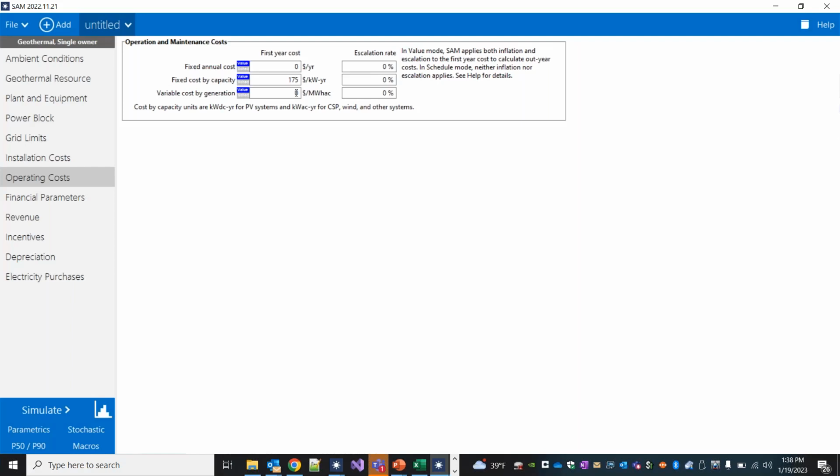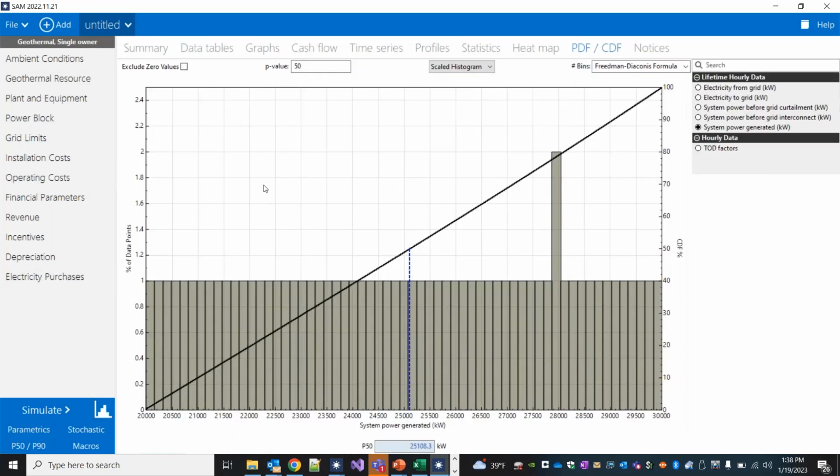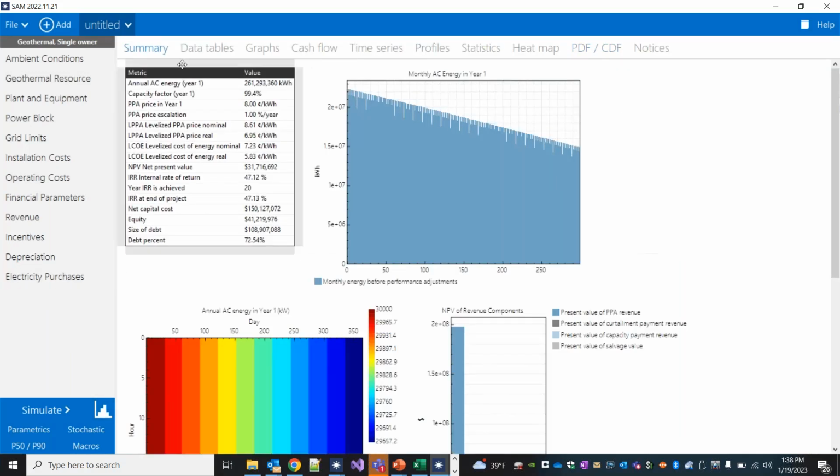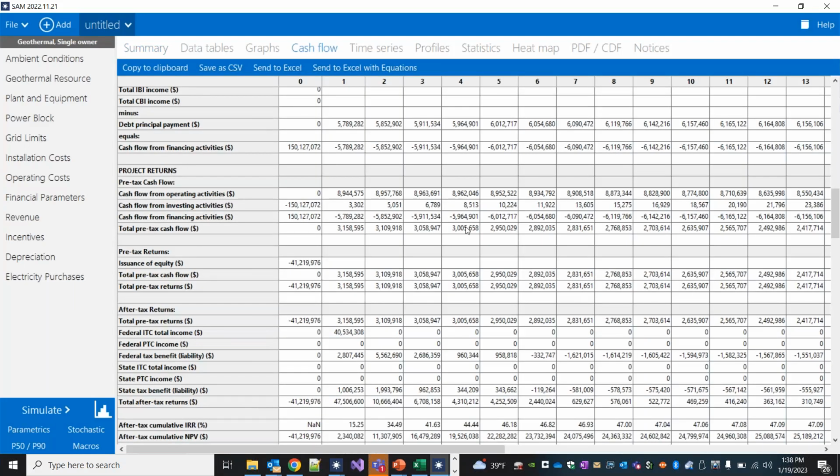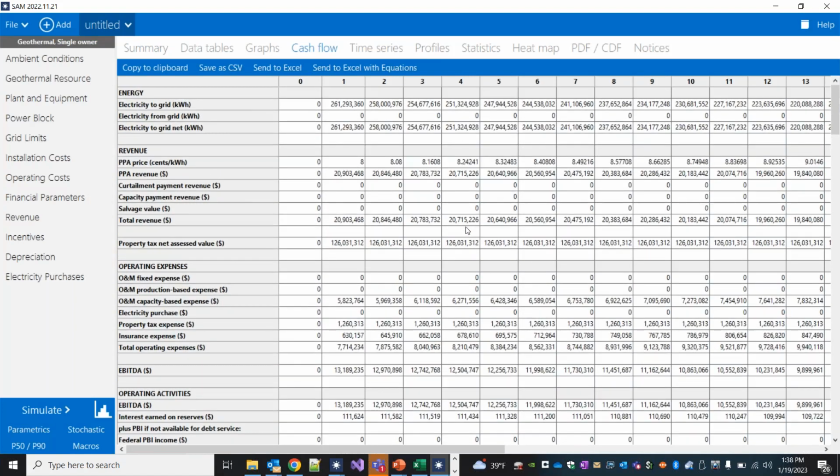And then the other related part of that question is on the results tab, with capital costs per kilowatt broken down by category. So, I think in general, as Matt mentioned, the cost inputs in SAM, both for installation and operating costs, SAM doesn't have a detailed cost model. So if you've got an external cost model, the idea is you would roll up the cost from your detailed cost model into the higher level costs that SAM requires as input.